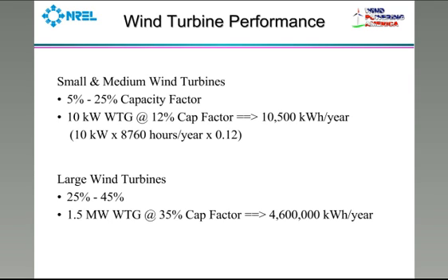Talk a little bit about expected wind turbine performance. What are some metrics that are kind of common? We use a term, it's more used for large wind turbines than for small ones, but the same concept applies, called capacity factor. And what the capacity factor is, it's what the wind turbine produces long term, say over the course of a year, divided by what it would produce over the course of the year if it produced at full rated power. And it makes it easy to plug it in, it's a shorthand way for showing wind farm production that you can plug into an economic analysis.